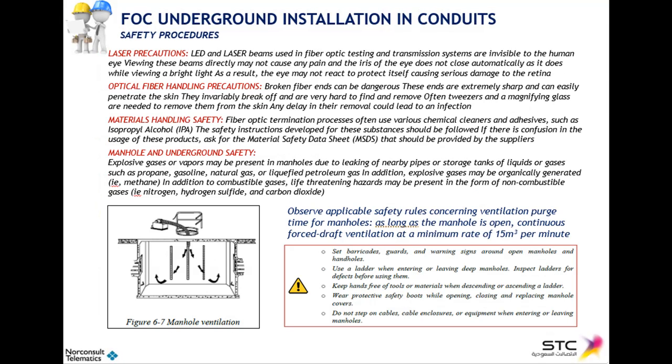On this slide, we're going to see some safety procedures while installing cables underground. The first point that we have to highlight here is to warn you about fibers that may transport light outside the visible spectrum, so you would be unable to see the light coming out. And if you look directly at the fiber end or at a connector, that may severely harm your eyes. So never ever look at the end of a fiber or a connector.